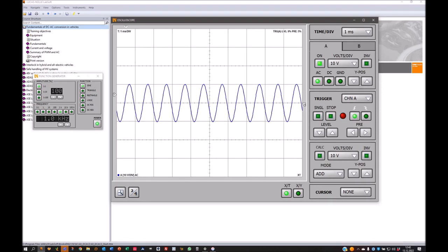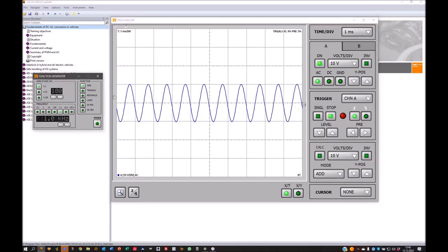Normally we can also adjust the position of the trigger with these buttons here, but we don't have to when we use this view, as we can then directly use the adjustments over here. When we now go to single, it will directly go to stop because it catches the signal and then stops the signal. So let's go back. I can directly go to stop now, and when I do stop, I can even deactivate the signal. You see it here, the signal is still present as this picture is frozen.